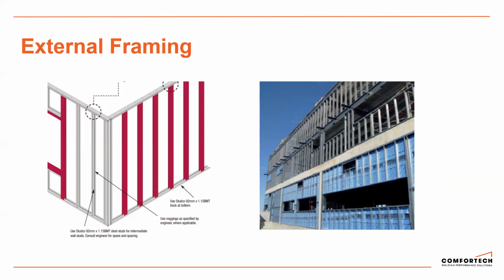In Australia, steel stud is very commonly used in external framing. In New Zealand, we've traditionally defaulted back to timber, because primarily it's a main contractor doing these partitions. Steel stud has a number of benefits, especially when we're talking high-rise buildings, in terms of non-combustibility. So it's a really good way of showing compliance and having a non-combustible product. Again, these are engineered designs where we get Stubco's engineers involved with this type of partitioning.